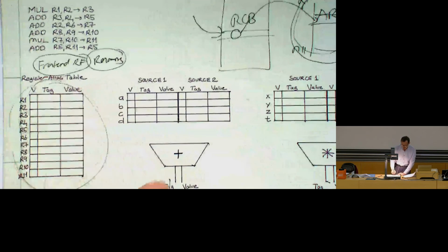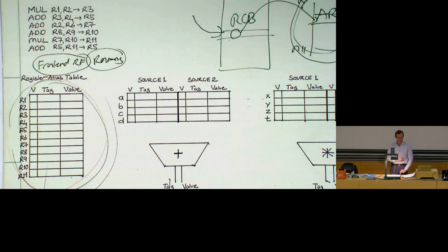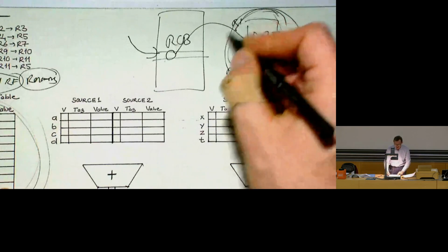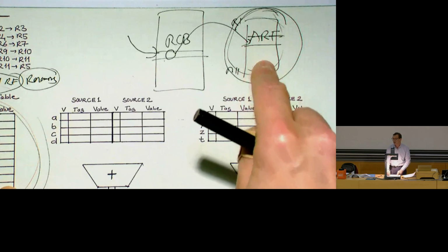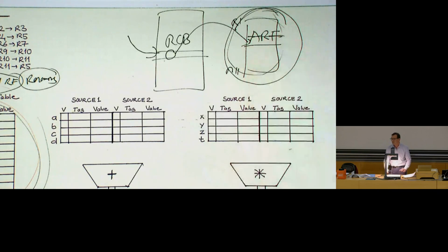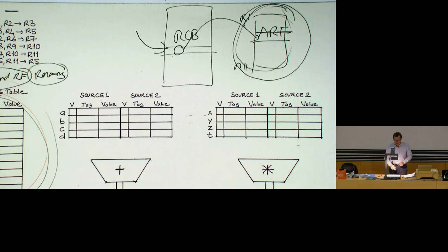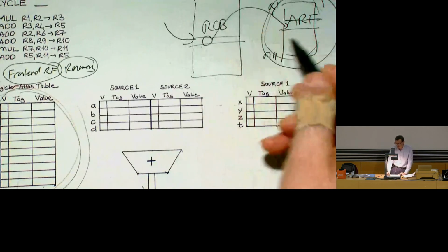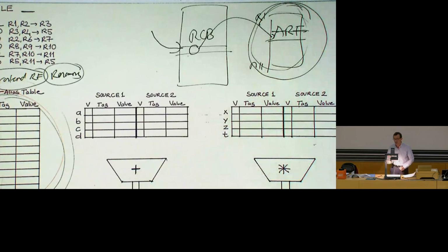This is completely microarchitectural, it's not visible to the programmer. So you don't have imprecise exceptions anymore because this is what really matters. It's always updated in program order. So that's the solution. This is very similar to what we've seen with the reorder buffer, and the reorder buffer enables us to update this register file in program order.